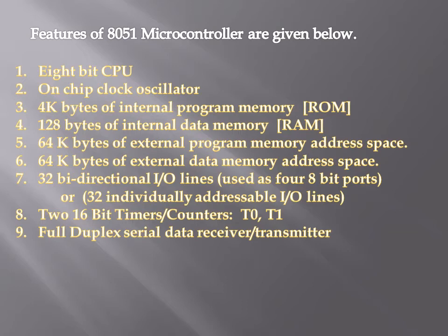The ports can be individually addressed, or bits can be individually addressed as 32 I/O lines. There are two counters, T0 and T1, 16-bit counters or timers, and for the serial data transmission and receiving system, we have duplex serial communication available.